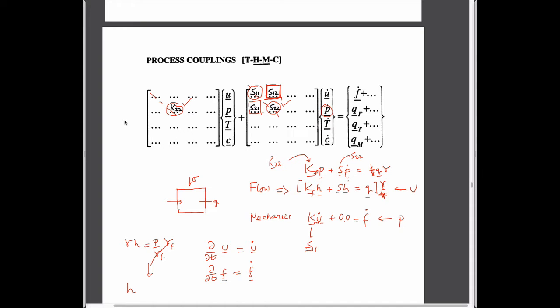And so we said already that the terms of this whole equation here, the continuity and flow equation, the term k d2h dx squared is in terms of a mass flux per unit volume. It's meters cubed per time per meters cubed. And so really what this displacement rate would give us would be a rate of squeezing fluid in terms of a volume per unit time per unit volume.